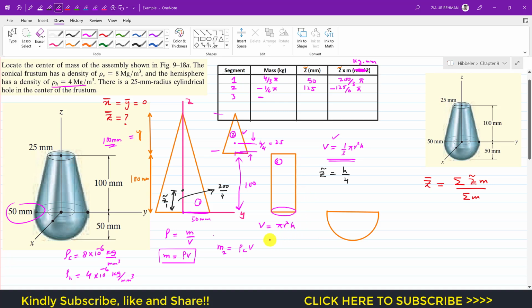Since it's part of the cone, we will use the density of the cone, that is 8 into 10 raised to the power minus 6, and the volume is pi, and the radius of this hole is 25 mm, since it's given that the radius is 25 mm for the cylindrical hole. So that is 25 square, and the height is 100. Remember, the hole has a height of 100 mm, so I will multiply it with 100.